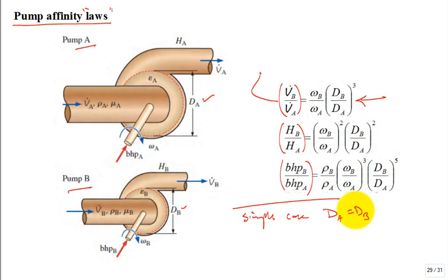Remember we had that variable frequency drive? Those variable frequency drives can go from 100% to a little bit more. They can actually make it go faster. So maybe they can go to 105 or 110% of the nominal speed. Okay, so they could change the speed. That's very, very common, and of the same pump.